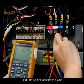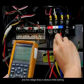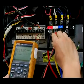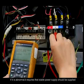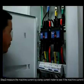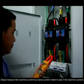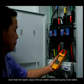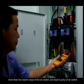Step 1. Check if the input power supply is stable and if the voltage drop is obvious while starting. If it is abnormal, a stable power supply should be provided. Step 2. Measure the machine current with a clamp current meter to see if the machine current is more than the maximum value of the air switch, which leads to the air switch jumping.